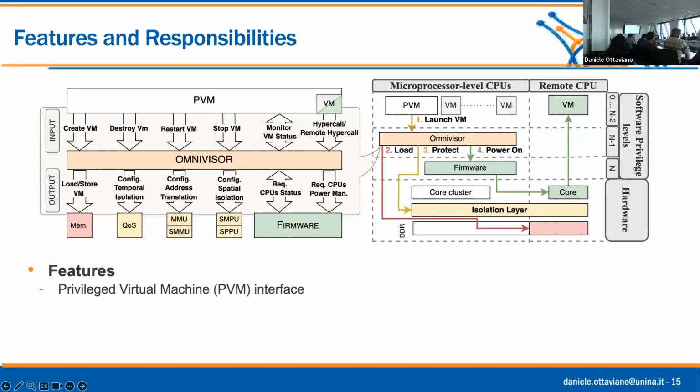In fact, they even bypass secure, non-secure privileges, right? They can access memories that are also marked as TrustZone secure, right? Yeah, exactly. We had some examples of this. So basically, if you use static partitioning virtualization, and inside the virtual machine you give access to the remote processor, which is considered I/O in all effect, you can, with that virtual machine, run whatever on this core, and the core is going to access wherever on the board. Also TrustZone-protected areas.